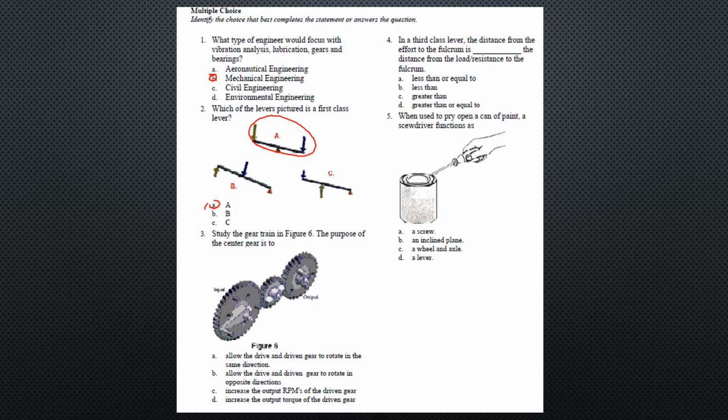Number 3, study the gear train. The purpose of the center gear is what? Center gear is the idler gear. All that is going to do is A, allow the drive and driven gear to rotate in the same direction.